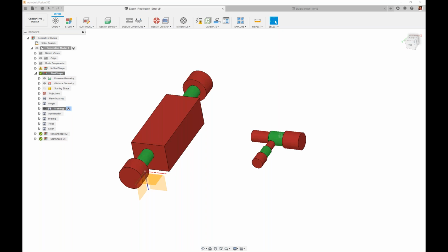We should also mention that when you get the outcome from the generative design, you can take it from within Fusion, as Apollo demonstrated in the product demo, exporting it back to the design environment. In the design environment, you could certainly make changes to the geometry, but you could also go right into the Fusion simulation environment.